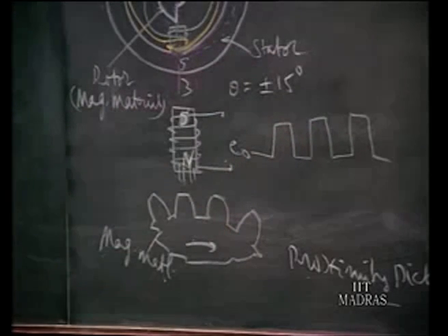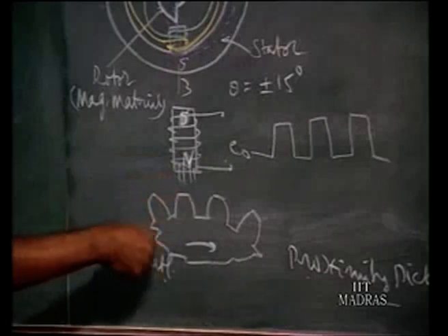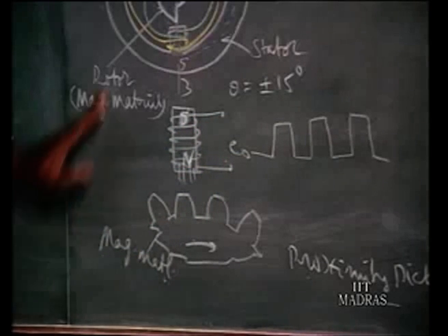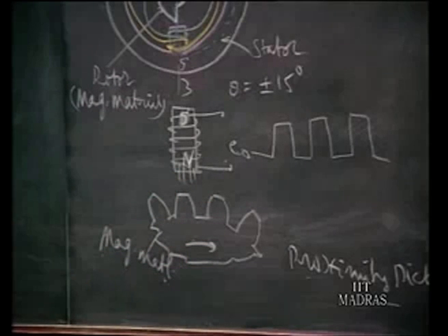It can be read with an electronic voltmeter and electronic counter, and you can divide by 100 to find how many rotations there were. That is how reluctance is made use of here in measuring the rotary motion of any magnetic material.